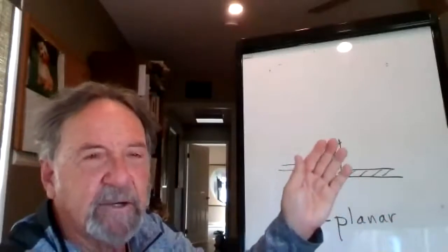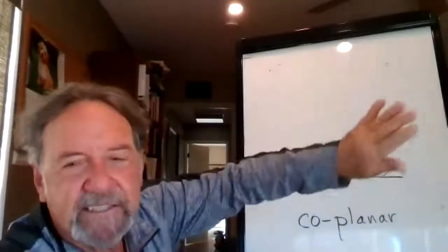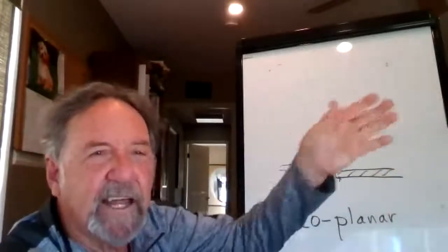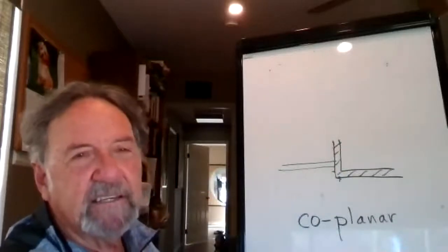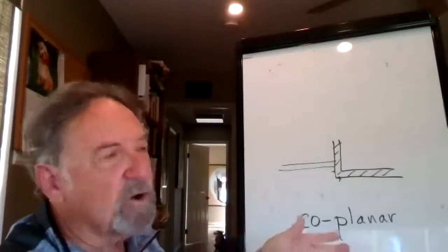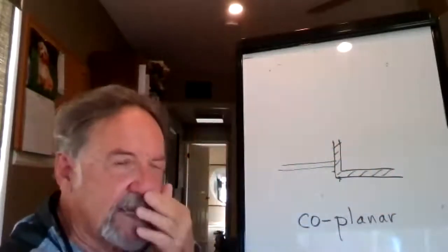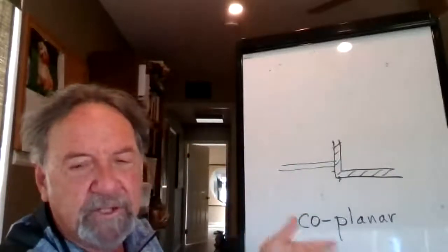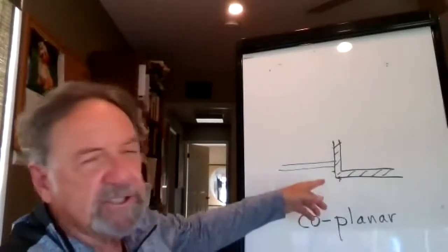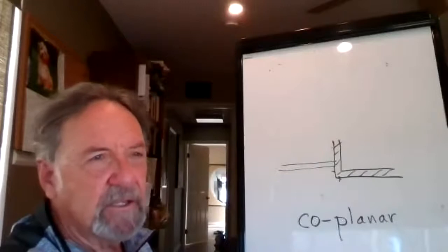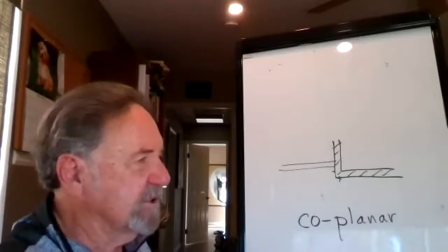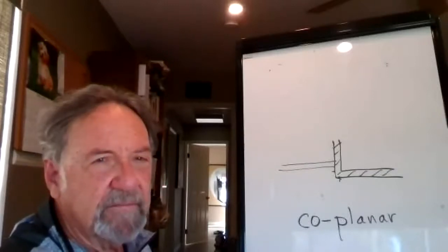If you do a coplanar with the same material, you've always got to worry about that joint. And if someone does a slightly crappy job, when the sun hits that stucco, looking straight on in the shade, you're not going to notice it. When the sun hits it and you're at an angle, you're going to see a line. So that's hard in sheetrock and anything where you're using the same surface. That's difficult. Good stucco people and good sheetrockers obviously can do it so you won't notice. But these are just ways you can avoid having to do that. So changing material, jogging the plane so it becomes two planes are ways to do that.